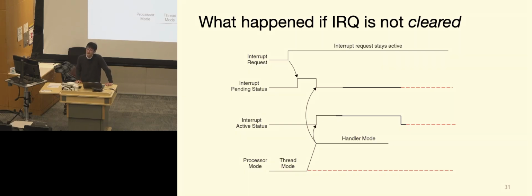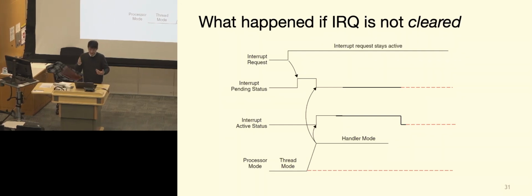It would stay low because there's no rising edge trigger again. But for the interrupt, it's still being requested, so it would be... Okay, we're getting closer. Any other addition? So basically, after the first ISR got executed, at the end of that, the program checked one more time to see if the ISR is still high, and that triggers it to go back to that register.